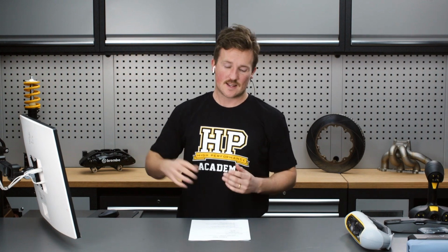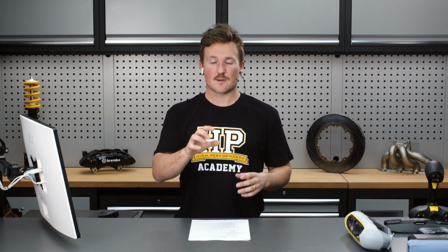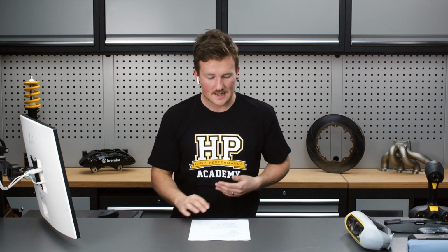So we have a big arm with different axes, and that has a little probe on the end of it, which can be placed on the surface of an object to measure its position in space. That doesn't rely on the scanner tracking its movement, because each one of those joints on the arm has an encoder in it, so it can continuously understand the position of the probe in space.